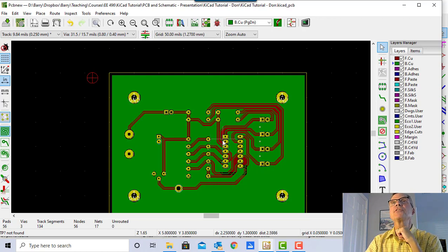So if I have solder resist between these pads, then I can go down here with a soldering iron, and it's extremely unlikely that I'll get short circuits. If I have this board that has this green solder resist on it.